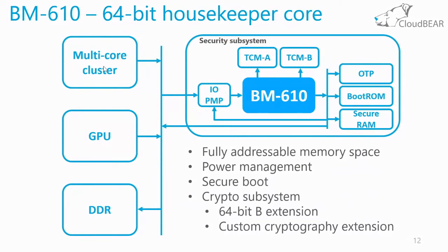Another application is also connected to secure boot, but here a smaller core was required, and the 64-bit requirement from the customer was mandatory, because the core should also manage a subsystem which has a 64-bit address space, and we need to support it inside the core to easily access it from the security subsystem.